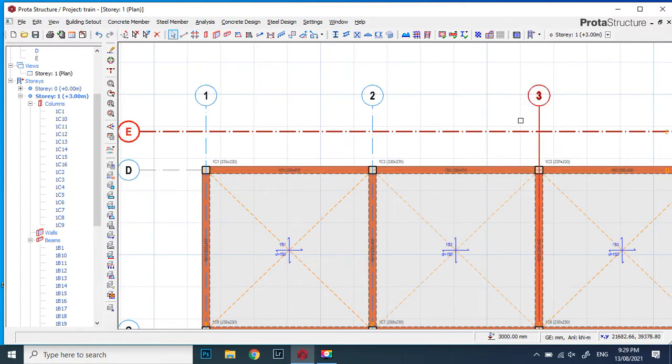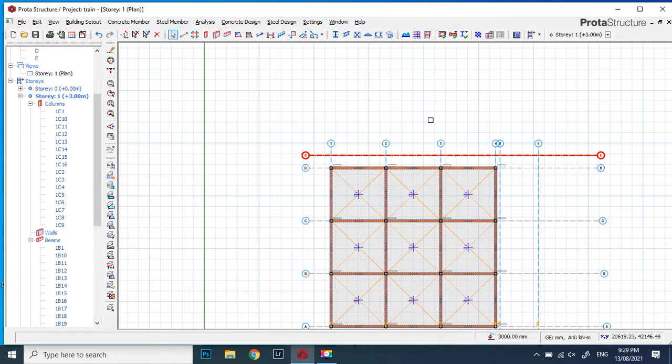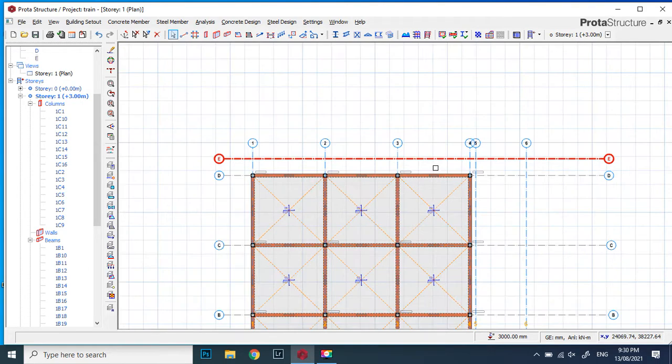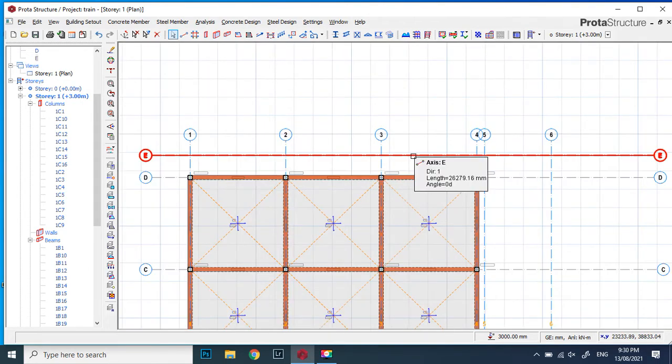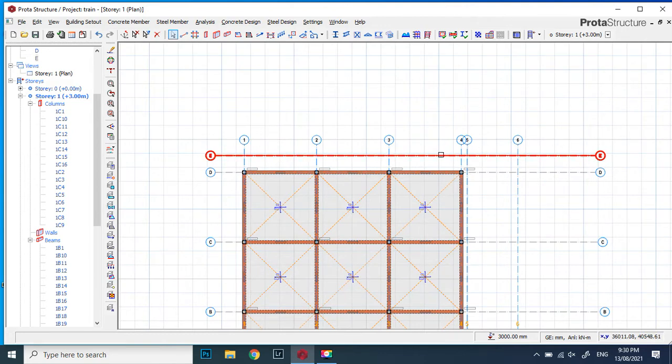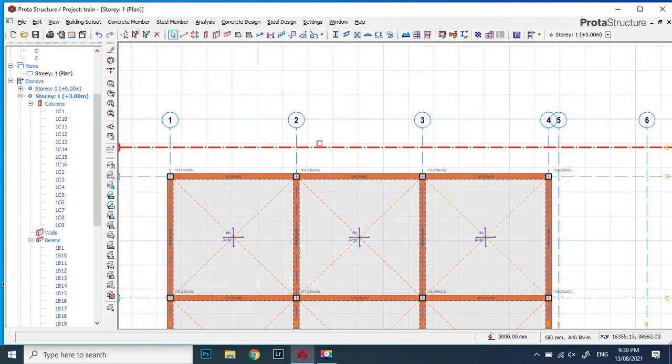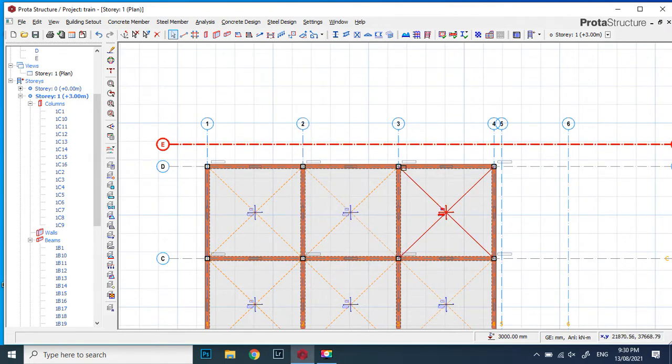That is very important. Please pay attention. Ismail Roto and Shina Adebayo, please pay attention to this. The first thing you need to create when creating your cantilever is the grid line. Make sure you create the grid line to where you want your cantilever to be or to stop. Now we've created that, I will show you two ways of doing this.